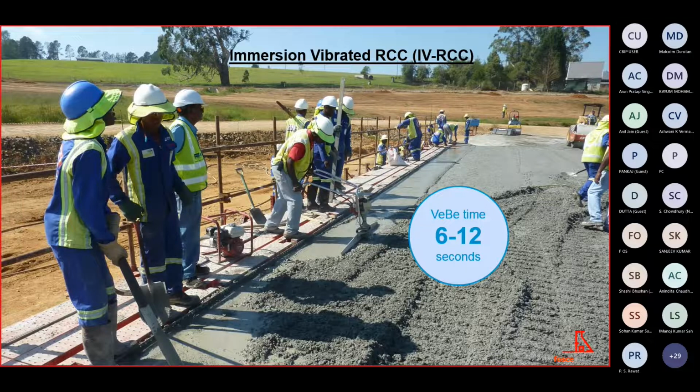All concretes in this picture correspond to the same mix, and no grout, no mortar, bedding concrete or conventional concrete mixes are added. The spread and uncompacted RCC is visible on the right near side. The high paste roller compacted surface can be appreciated at the back, and the immersion vibration against the formed face is running on the left side, followed in this particular layer by a hand-held vibrating screed easily finishing the top surface of the future downstream steps.